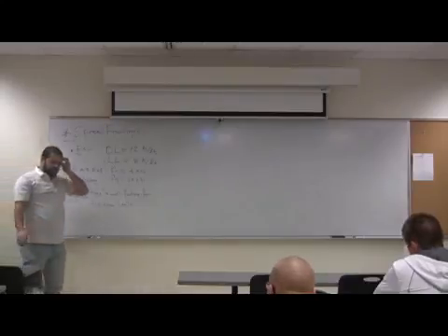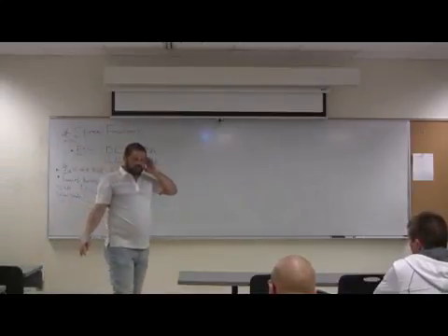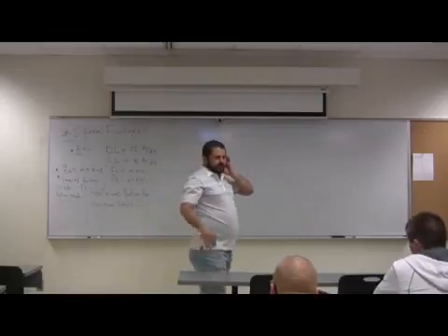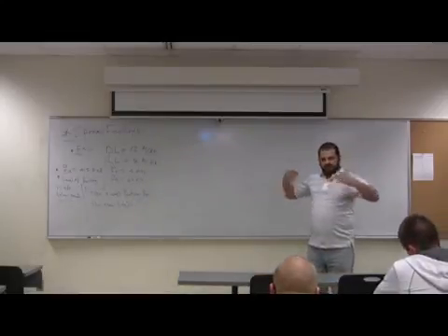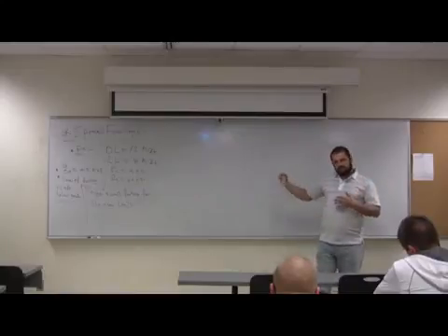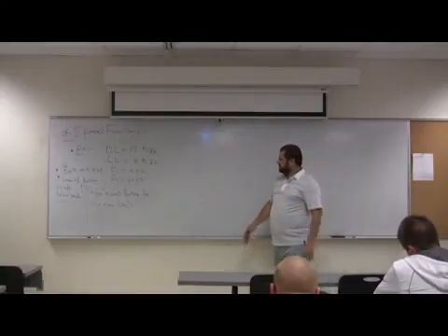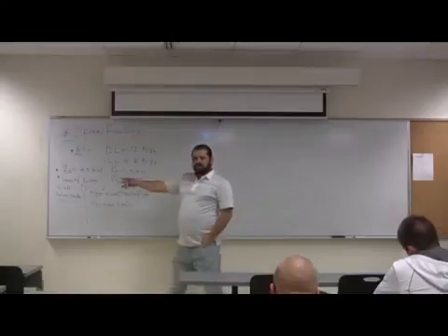By the way, just one more information. Typical wall footings, 1 foot, 1.5, 1 foot. That's typical thickness. But we're gonna check it. But if you want to start the first assumption to check, assume 1 foot. Okay? You know what I'm saying here?